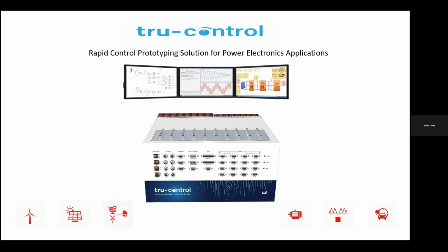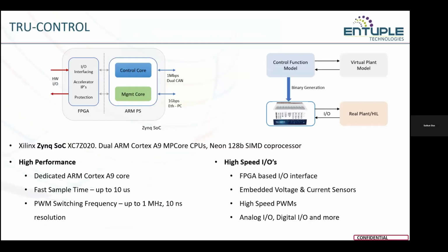So all these points I'm going to discuss in the upcoming slide. Now, TrueControl is based on the Xilinx Zynq system on chip device. In a system on chip device, it contains an FPGA as well as ARM processors. We are using the FPGA for IO interfacing because we want high speed IO interfaces, and the protections run on the FPGA independently from the control logic.